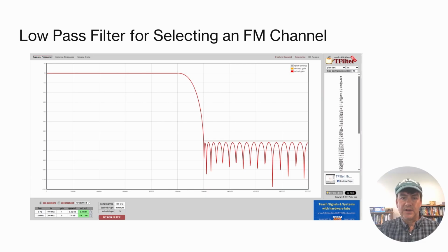According to the SDR diagram, the sampling rate is 160 MHz, which is far higher than required for audio processing and strongly motivates the use of decimation filters. In addition, the filter design requires specifying the allowable passband ripple and stopband attenuation.